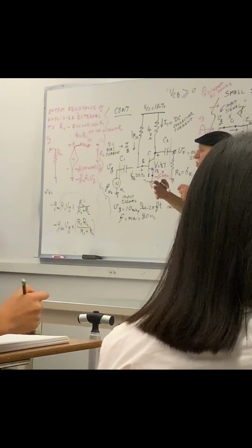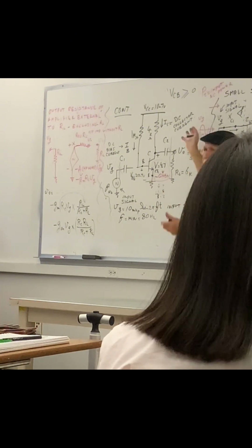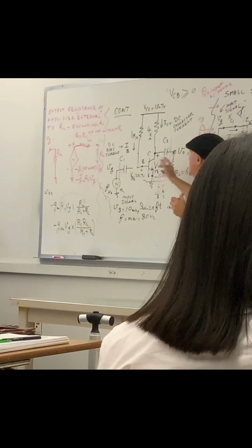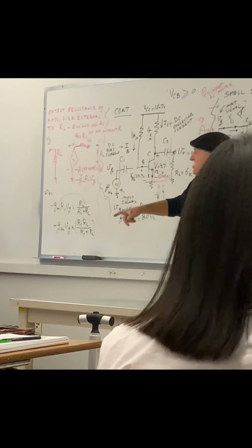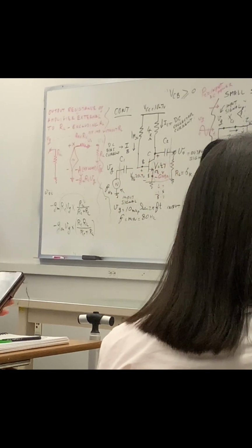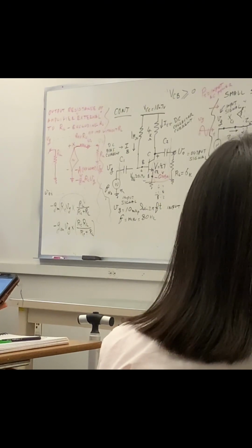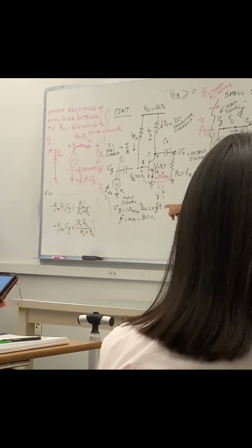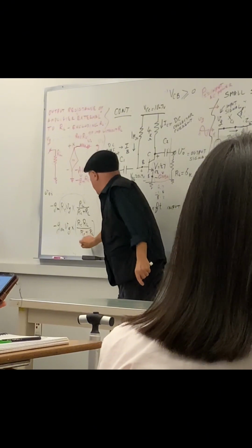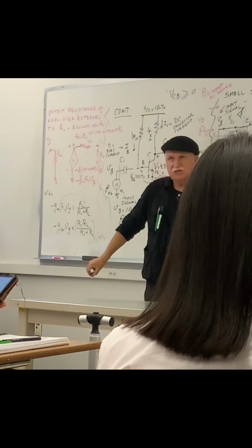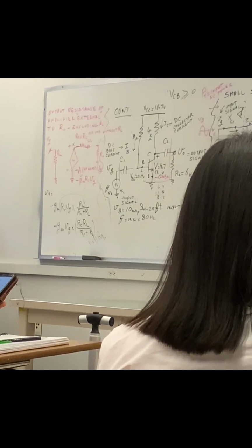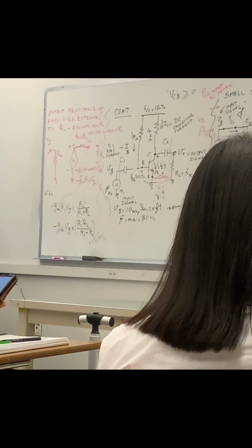So you have to see what the situation is. If there is no second amplifier and so on, you can go at once, use that gain, loaded gain, which is input to the output. This is the formula. RC parallel RL, which I proved here. See? This is RC parallel RL, which is exactly this formula. This is known as the loaded voltage gain. This guy.